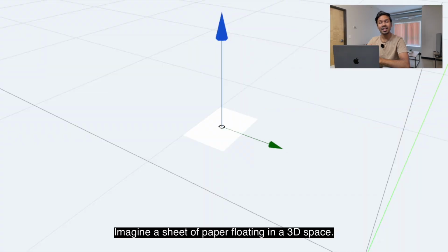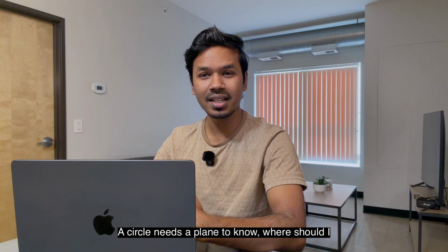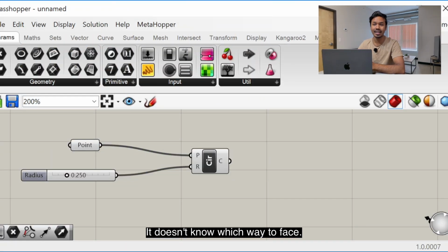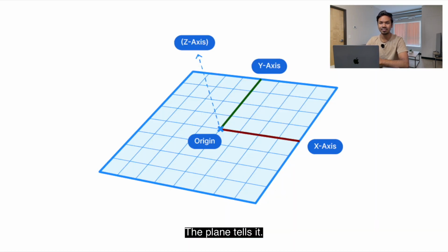Let me explain. What is a plane? Imagine a sheet of paper floating in 3D space. It's flat, it has a center point, the origin of the plane, and it is known which direction is up relative to itself. A circle needs a plane to know where should I be drawn and which way should I face. If you just give a circle a point, it doesn't know which way to face. Should it lie flat, stand vertically or face diagonally? The plane tells it. Here is my origin and here is my orientation.